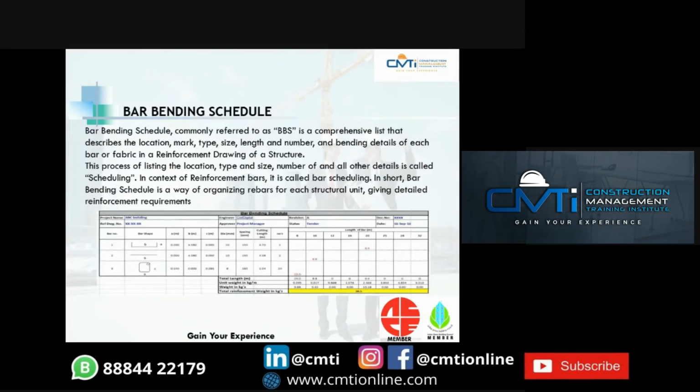Next, we'll discuss the bar bending schedule (BBS). The bar bending schedule, commonly referred to as BBS, is a comprehensive list that describes the location, mark, type, size, length, number, and bending details of each bar or fabric in a reinforcement drawing of a structure. So, BBS is very important. In it there will be all the details about the bar bending, like the location where the project is taking place, the mark, the type, the size of the bars, the length of the bars, how many bars are required, and all the bending details.